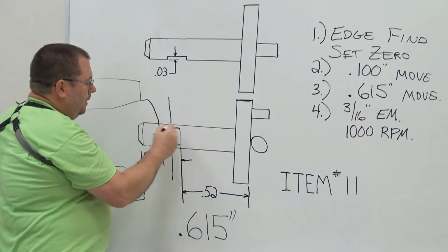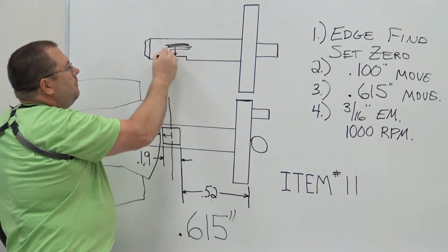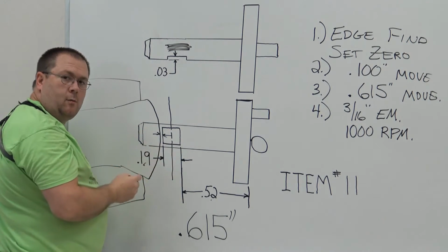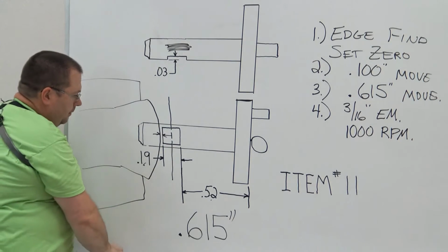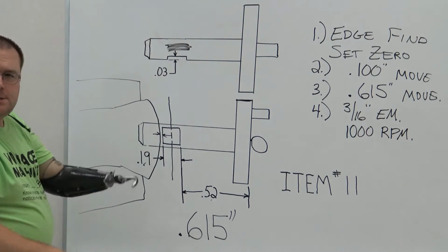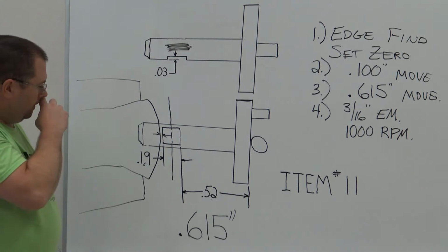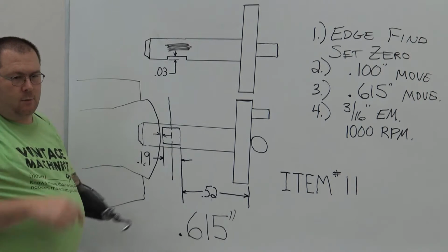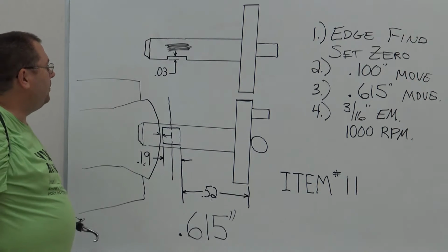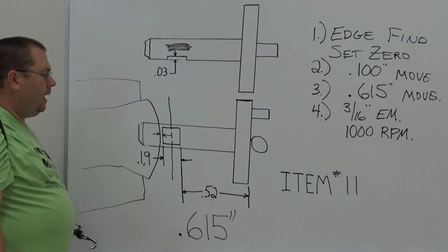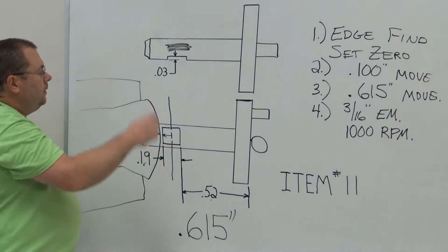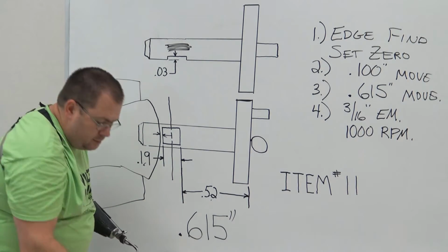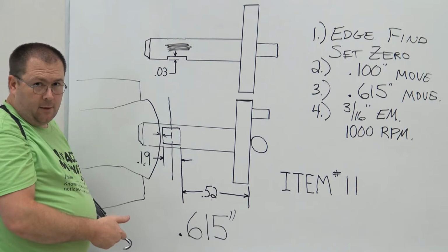Now we're going to come down and I'm going to color. I'm going to take my Sharpie and color that surface. Okay? We're actually down here, but I don't want to color over what I care about. So we're going to come down until it just touches. Okay? Lock your x-axis in because the movement of the table may get away from you. Likely not, but I'd rather be safe than sorry. So we're going to lock our x-axis. Here, come down and touch the top surface of the part. Set my dial on my knee, which is that big crank, to 0.